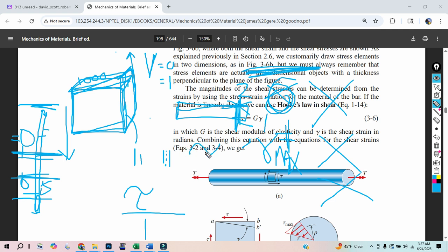And then the shear stress, that's force per area. Shear max, that's the max, and they just use it in the engineering sense. That's the highest end of the linear range. After the linear range, you are going to get permanent bending. Your tool is going to be bent. Your bridge is going to be bent permanently.